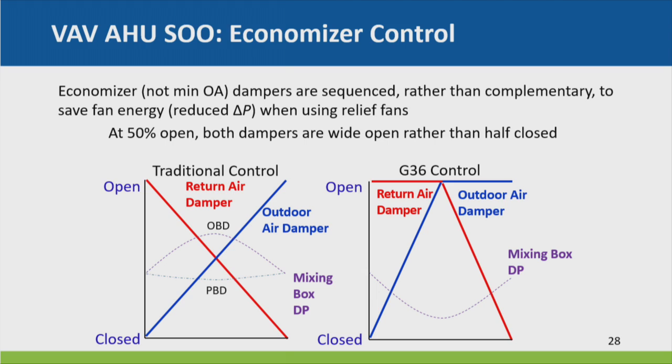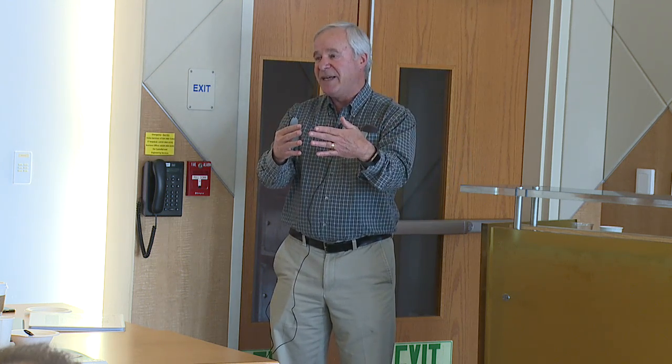Somebody said, yeah, but does it mix as well? So we did another research project on that, and found that it actually mixes better, because now the two airstreams are blowing straight, as opposed to getting deflected by the vanes of the dampers, and so it actually mixed a little better. But when you're at 50%, mixing doesn't really matter usually all that much, right? That's when the air is not that cold.